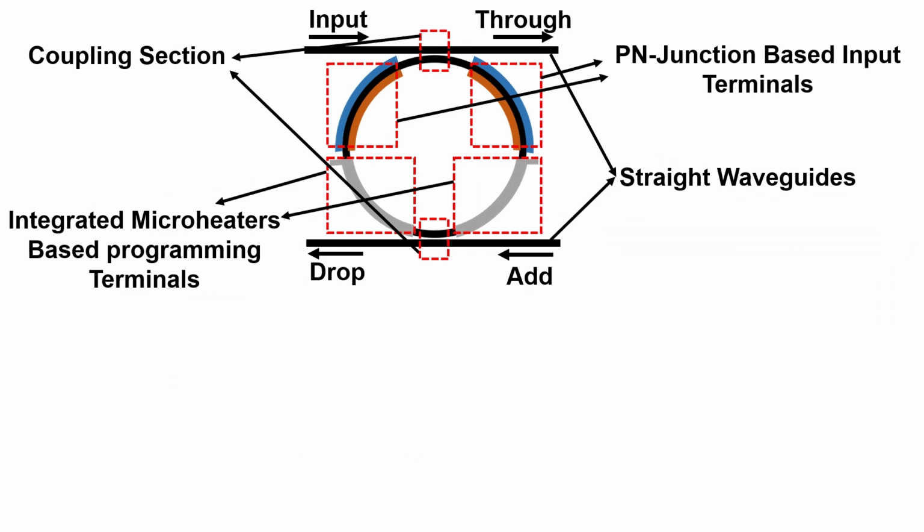Now, to design and simulate this device using Ansys Lumerical suite, we have to break this device down into a set of primitive elements, as you can see here. We use different solvers in the Ansys Lumerical suite to model each primitive element. From these models, we extract various parameters corresponding to each primitive element. Later, we combine all of the extracted parameters in Ansys Lumerical's interconnect tool to create this device. Then we perform the frequency domain and time domain transient simulations of this device.